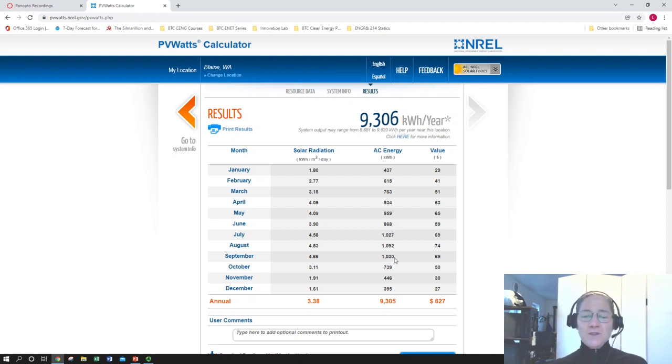But if this person is only concerned with the winter, maybe the 1,000 kilowatt hours of summer production is way in excess of what they use in the summer. And in fact, in many winter climates, a winter demand-dominated profile is pretty typical. They're going to want to configure and optimize their system to maximize those low numbers, knowing that that same system will be more than adequate to serve their needs in the summer months.